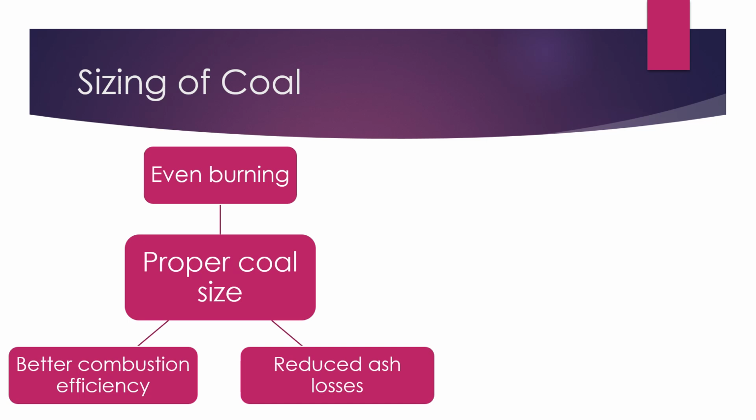The size of coal is reduced by crushing and pulverizing. The size of coal becomes 4 to 6 mm after crushing. Rotary breaker, roll crusher, and hammer mill are used for crushing of coal. Bigger size coal is screened or filtered before introducing it into the crusher so that only the required size is allowed into the crusher. This reduces power consumption of the crusher. A magnetic separator is introduced before the crusher to avoid damage to the crusher by iron items.